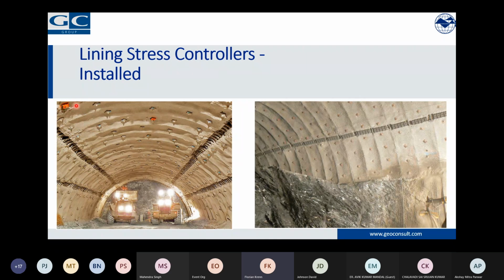There is sometimes, as a first measure, when there are larger deformations, you can put two steel pipes basically between the sprayed concrete and the plate, the face plate. And this also acts like a, so to say, rock bolt stress controller, because first the two tubes have to be crushed and then the full load will come onto the plate. So this is when we expect high deformations.